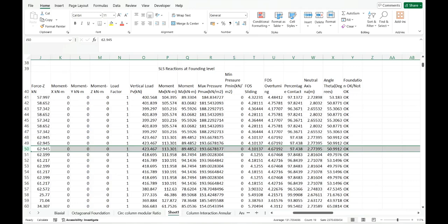So ideally, it is prudent to check that combination, and many a time we might slip that combination. So ideally, we need to consider it, especially for lateral load cases. That's right. So this is a more robust way of checking the foundation stability and the pressures. I think this is more applicable to tall structures, and also to slender structures with high wind loads or earthquake loads. That's true.